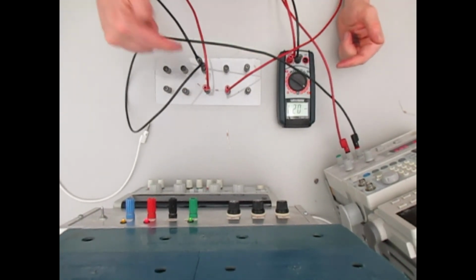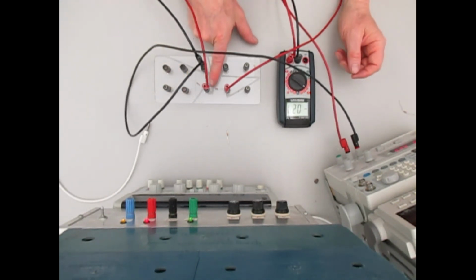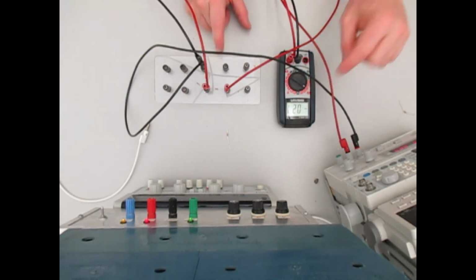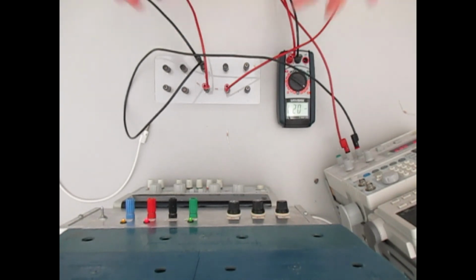And then when I measure here across, and this resistor is just hanging here, the voltage across the resistor is negative 0.27 volts. And in our superposition theorem, we measured it to be negative 0.26 volts. So again, it's almost exactly right on. So even with our 680 ohm and not a 705 ohm and our 470, all of this stuff is turning out almost exactly the way we want it, even though we're just kind of making stuff happen here.